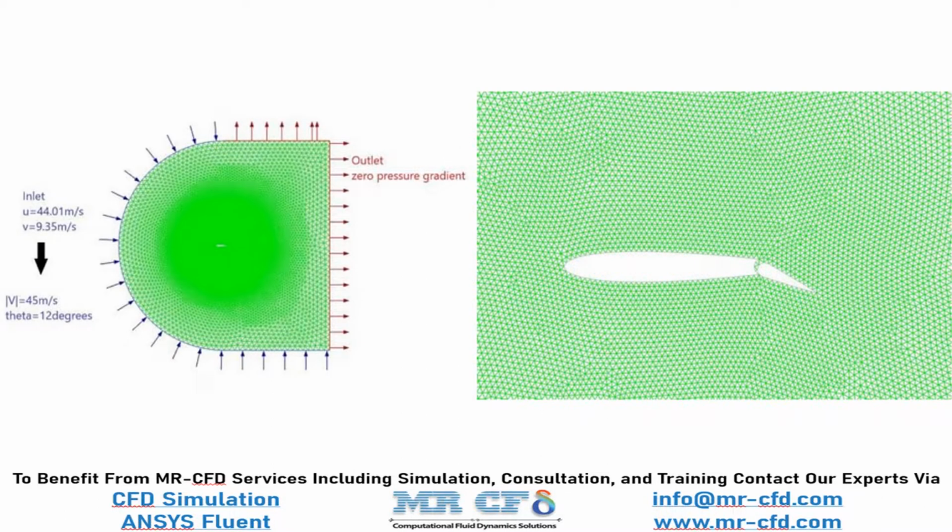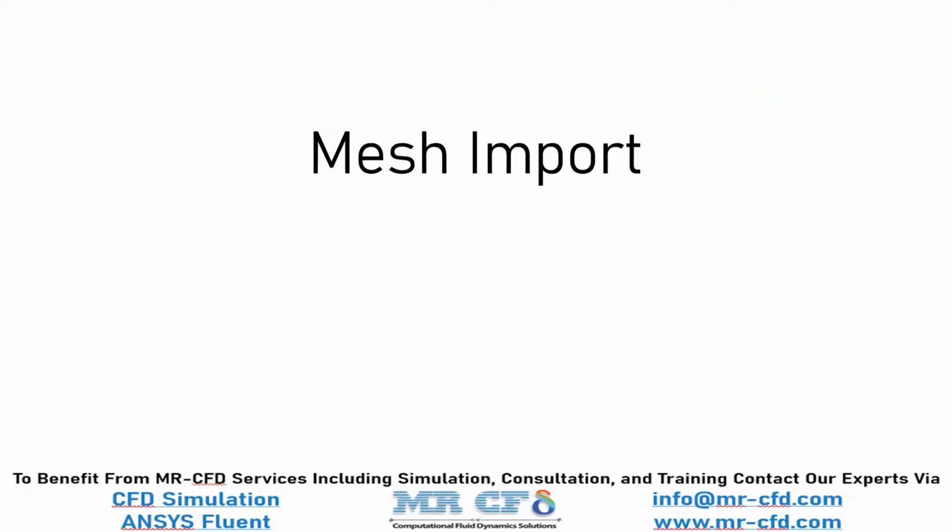The fluid domain's geometry is designed in the Design Modeler software, and the computational grid is generated using ANSYS meshing software. The mesh type is unstructured, and the element number is equal to 64,731.